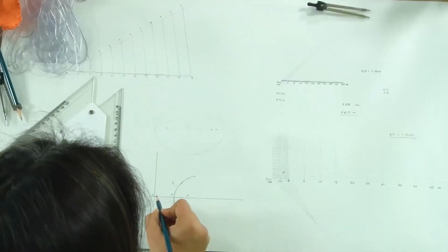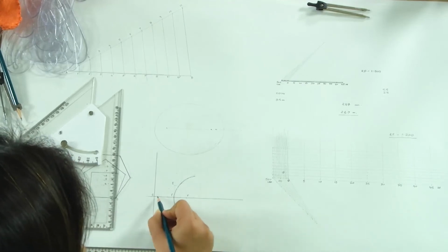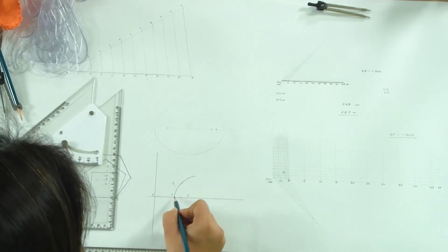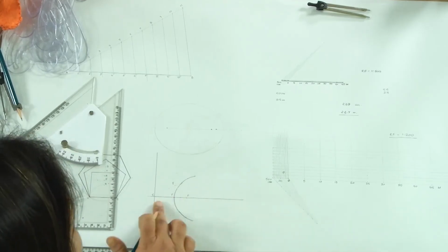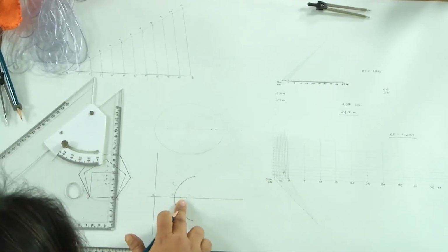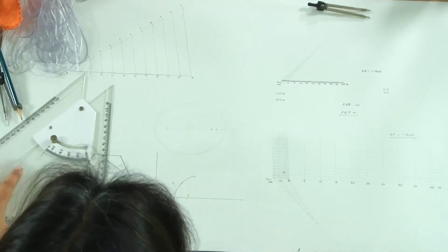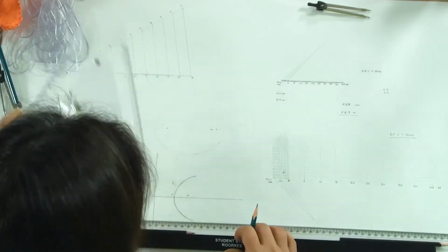The next one is a parabola. So now we'll draw a parabola. Drawing a parabola is very similar to how we draw an ellipse, the only difference being that the eccentricity of a parabola is always 1. So we know that this distance which we had taken between PC and PF, that the ratio is always going to be 1. So these two are going to be equal. So I'll quickly draw a parabola here.